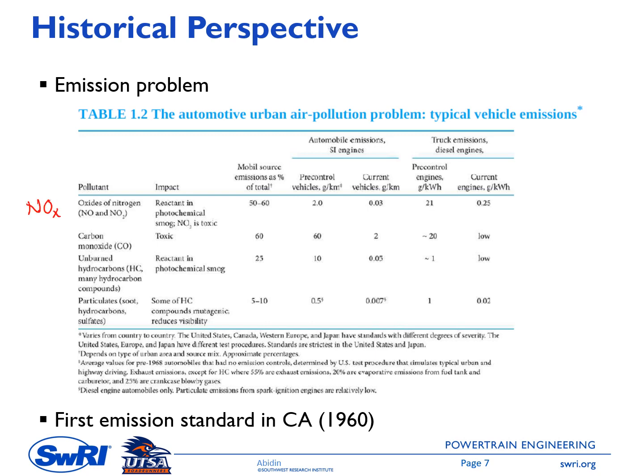The second one is carbon monoxide, CO, and then unburned hydrocarbon, which means fuel that is not burned in the engine and goes out of the engine along with other exhaust gas. The next one is particulates or soot, which is the typical emission from a diesel engine.